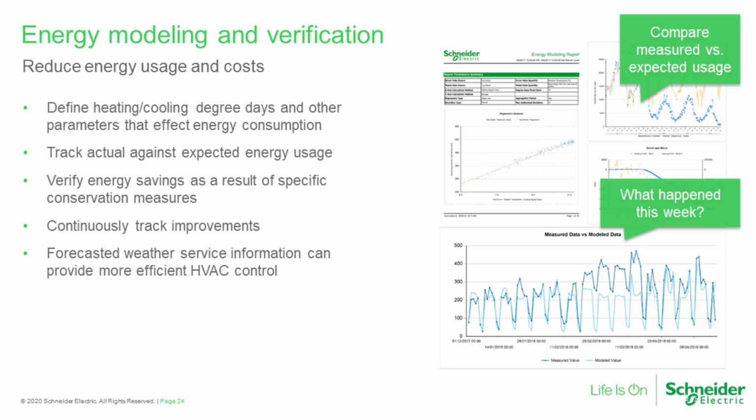Another benefit is tracking the return on investment accurately after, say, an energy efficiency project. If you put in new chillers and you want to assess the return on investment, what you can do is track the drift from the model and then quantify that drift. The variance from the model after you put in an energy efficiency program is really hard dollars that you've saved. And that's something that a facility manager can go back to management and say, this is the return on investment, and I can prove it. So that's also a very tangible